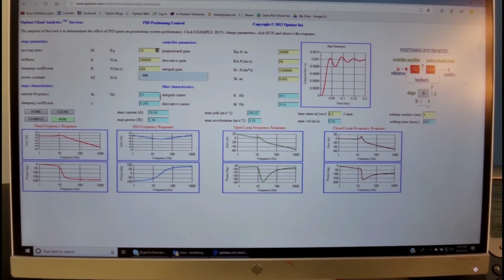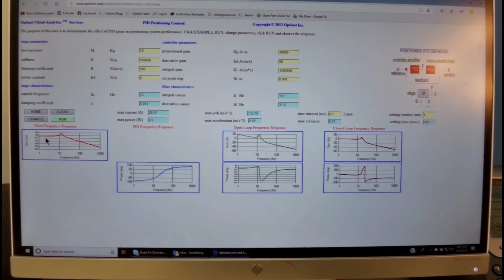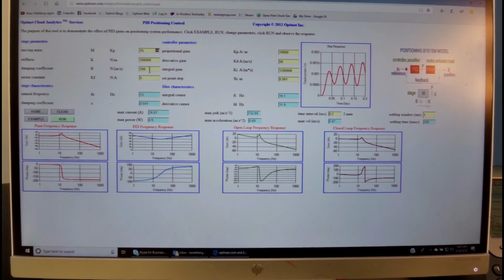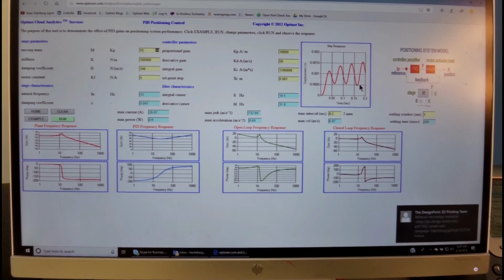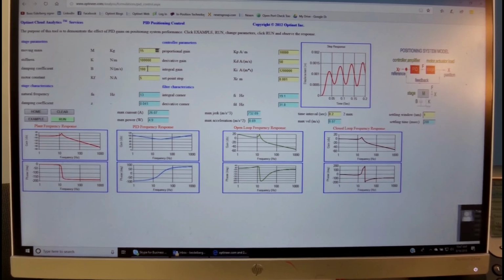If we decrease the number from where it was before, let's say to 100, then we will expect this peak to be of different configuration over here. So now we have a lower damping coefficient, so the peak over here is getting higher. As we see, there's less damping, the oscillations are getting higher, and the time also is changing.